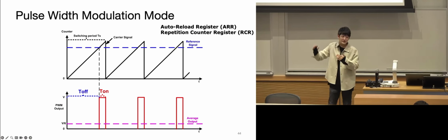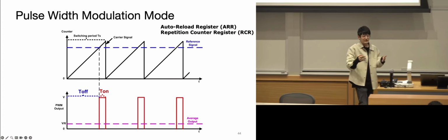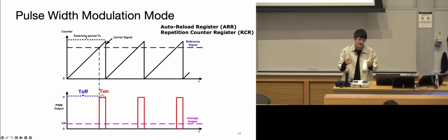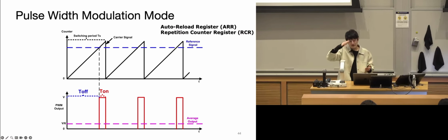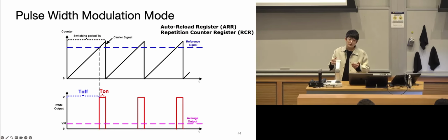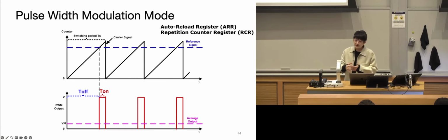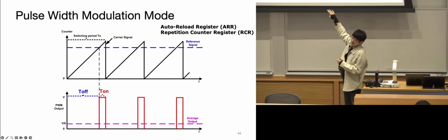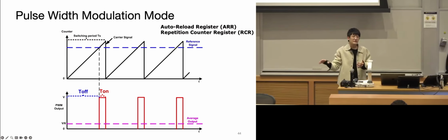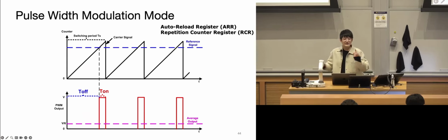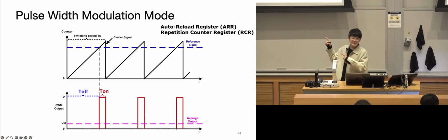So the duty cycle, when we generate it fast enough, will kind of work like an AC signal, but above 0, and that gives you an equilibrium DC voltage output. So if the frequency is fast enough, this is the equilibrium DC output from the device that it's connected to. We good on this part?